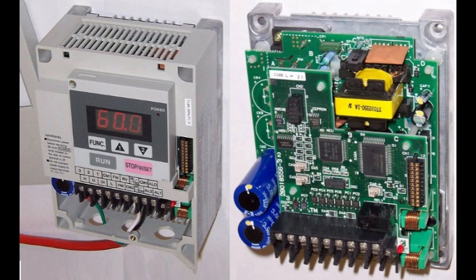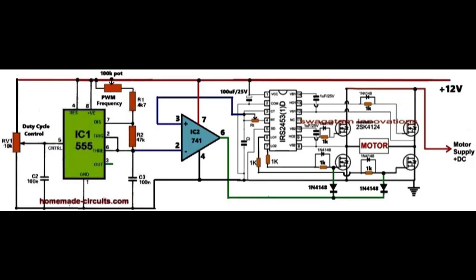Okay, so now that you know the actual purpose of a VFD circuit, let's understand our own VFD circuit diagram. Circuit description. Referring to the full circuit diagram shown on your screens, this VFD, or the variable frequency drive controller circuit, is exclusively designed by me, and the main objective of this VFD circuit is to provide a sine wave output with adjustable frequency and RMS voltage for controlling the speed of an AC motor as per the standard VFD specifications. Here's how each section works.